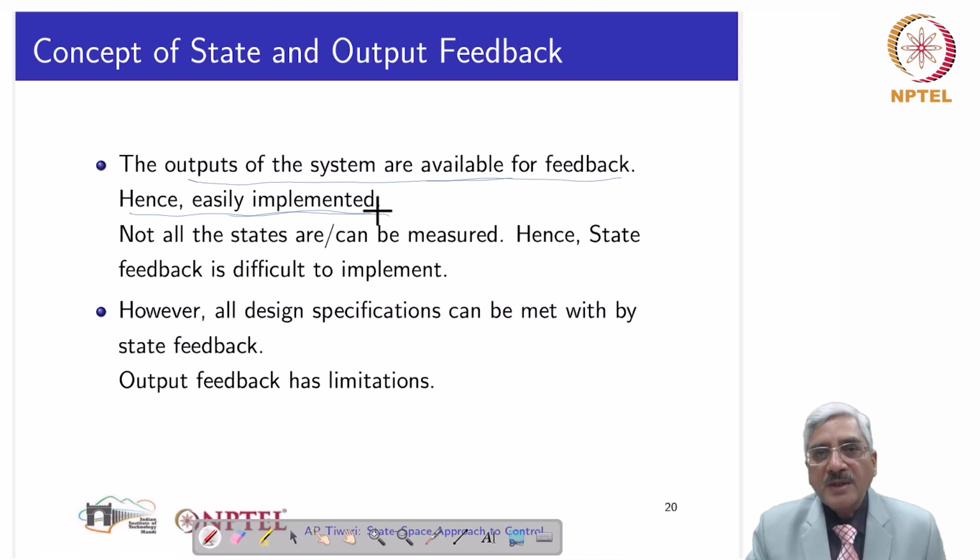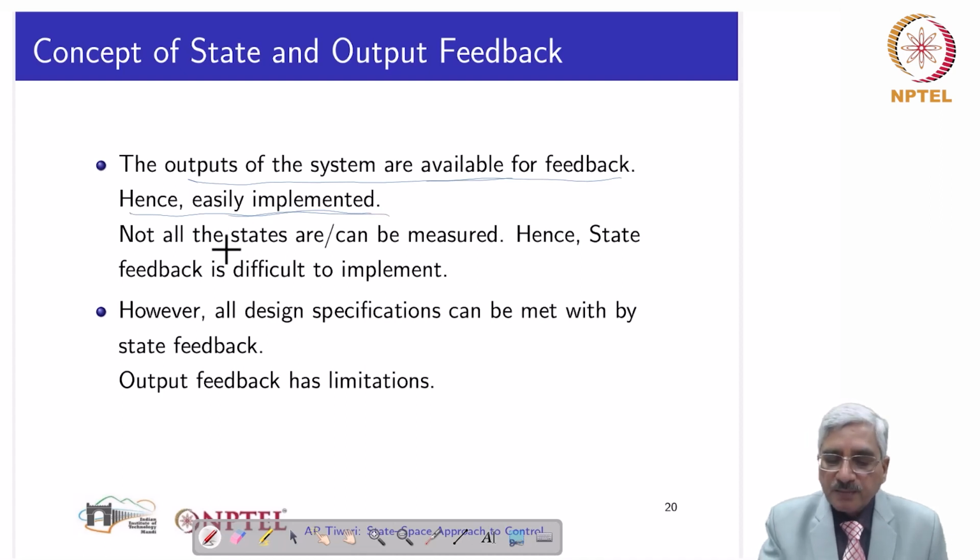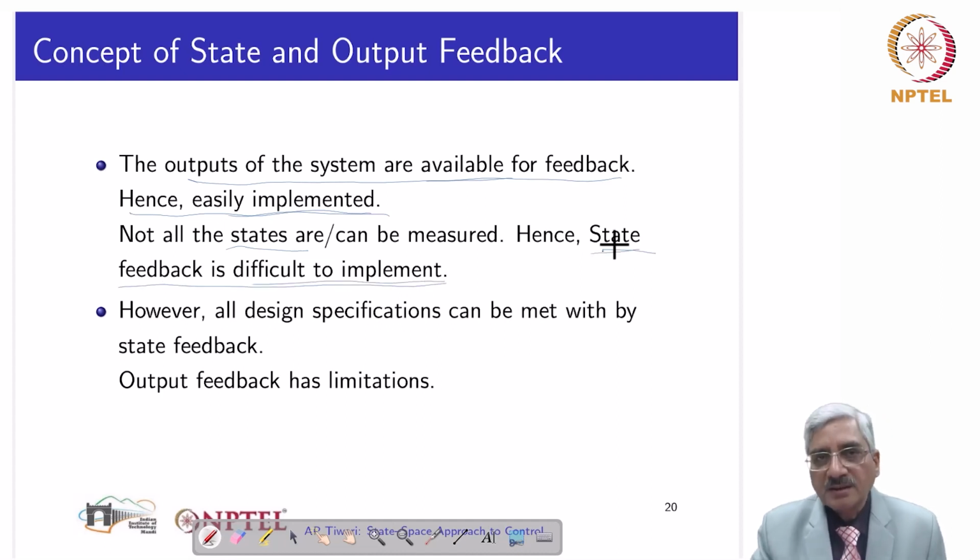Or even if it is possible to measure, putting instrumentation for all the states will be a very costly thing to do. So generally not all the states are available for feedback. Either they cannot be measured or they are not measured for economic and other reasons. So state feedback is difficult to implement. However, there are methods. Observers or state estimators can be designed. In that case, state feedback can also be implemented, but it increases the complexity.